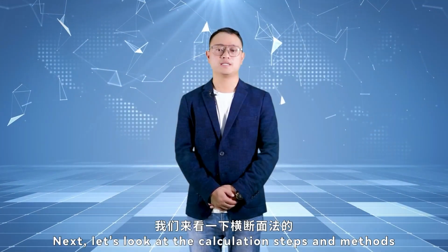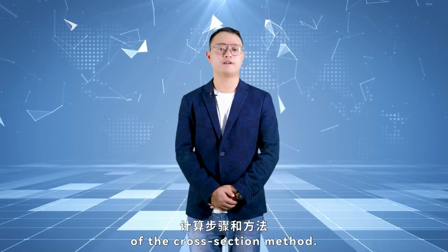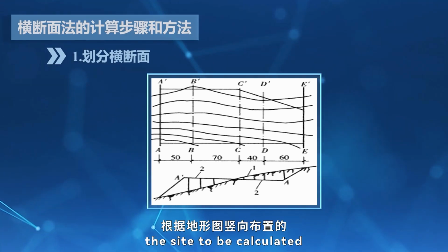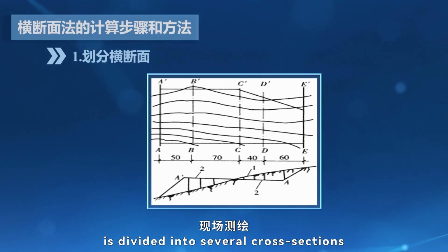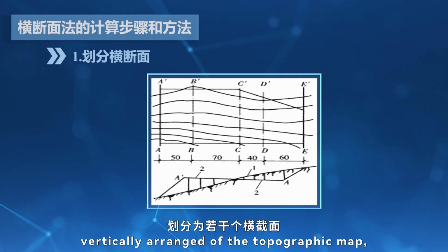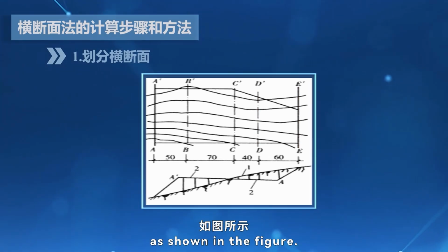Next, let's look at the calculation steps and the methods of the cross-section method. First, cross-section division. The site to be calculated is divided into several cross-sections according to the site surveying and mapping, vertically arranged on the topographic map, such as A-A, B-B, C-C, etc., as shown in the figure.